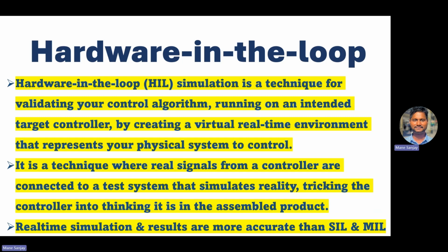HIL tests are executed with the final software and designated target hardware. The environment of the ECU can still be simulated. However, the data is transferred using appropriate converters to interact with the control unit via the electrical interface. The environment model must have so-called real-time behavior, which means the response of the model must be guaranteed within the specified time constraint. That's the beauty of hardware-in-the-loop simulation. This is to ensure a realistic test so that the communication with the ECU is the same as in the real environment.